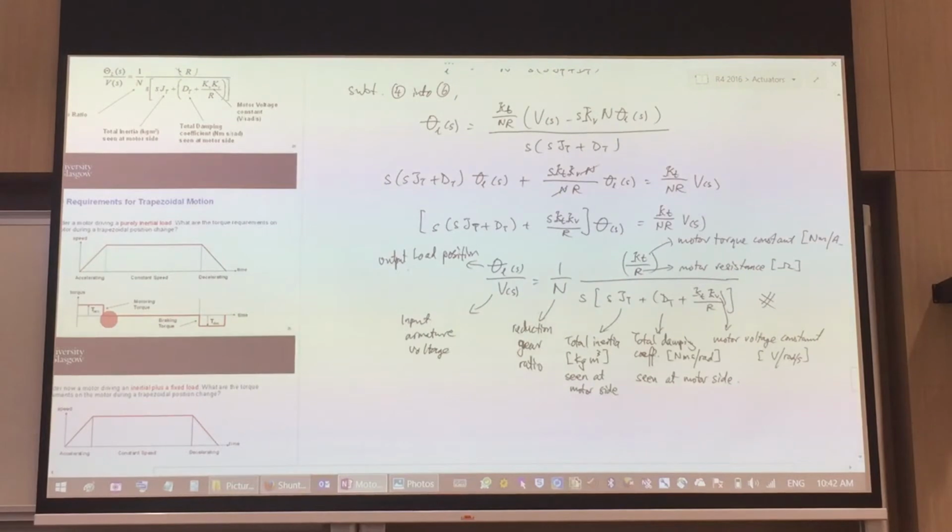So if you want the motor to ramp up its speed, it's not to apply a torque that ramps up. You apply a constant torque. So applying a constant torque, the motor will start to ramp up gradually. And as it ramps up to the level that you want, then you will stop applying that torque, zero torque, and then the motor will maintain that constant speed. And when you want to decelerate that, that's when you apply torque in the opposite direction, and you will decelerate.